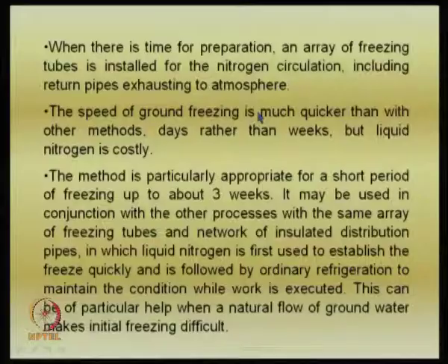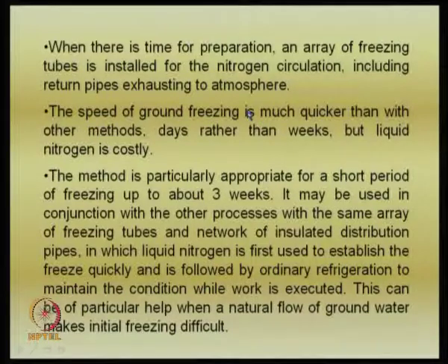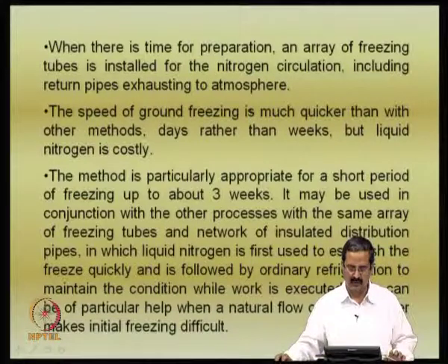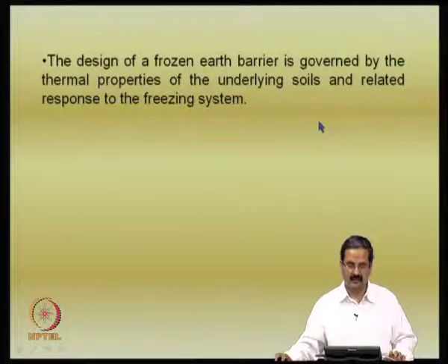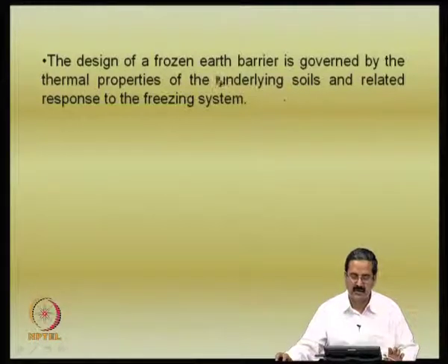So, as I just mentioned, the use of this freezing technique is something very tricky, and one should be able to design the system in such a way that you have a proper combination of primary cooling and secondary cooling systems, and also see that the circulation of coolant is proper, and that the so-called frozen earth barrier is maintained till it is required.